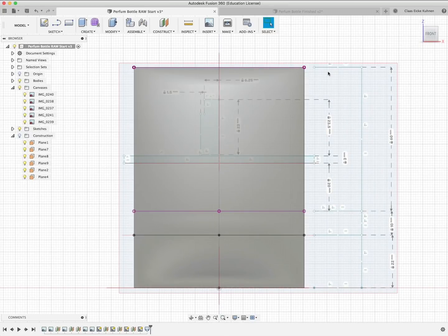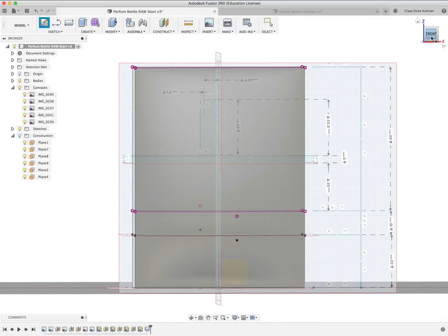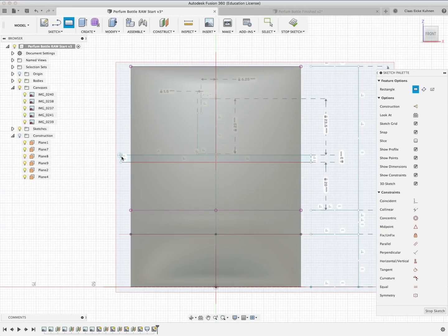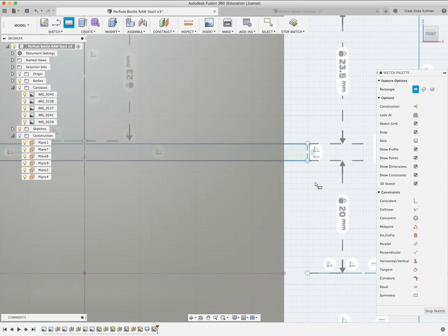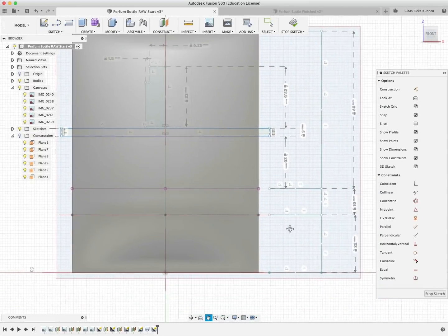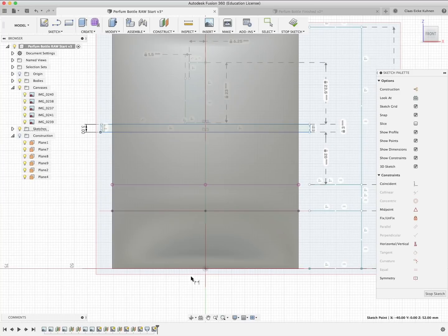In this screenshot I made, I can see right here there is a rectangle. This is actually right on a normal plane, so I can just make a new sketch directly onto the front and draw this rectangle there. This should be 3 millimeter height, very good. And then I see this is 52 millimeters from the ground. So I could say this point from the center point 52. Okay, very good.